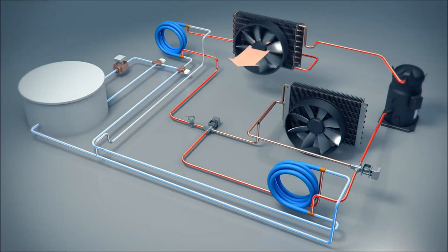The heat exchanger is defined by a refrigerant glycol interface, whereby heat is transferred from the glycol solution to the refrigerant. The refrigerant exits the heat exchanger at an elevated temperature and continues through the remaining components of the AC Companion stabilizing loop.